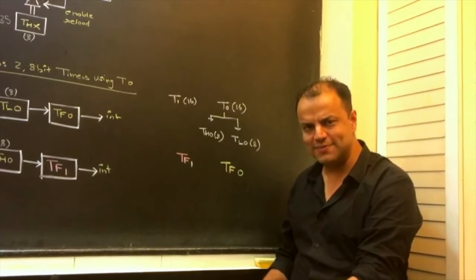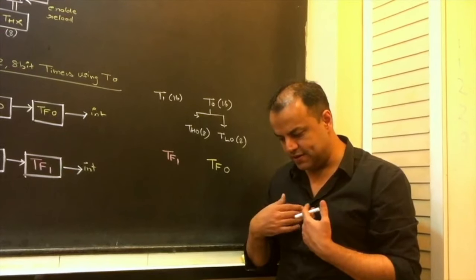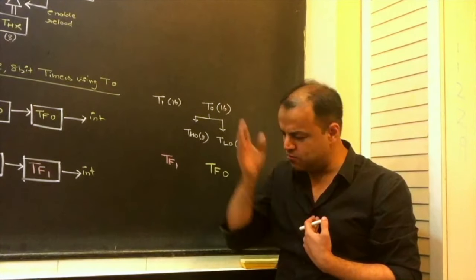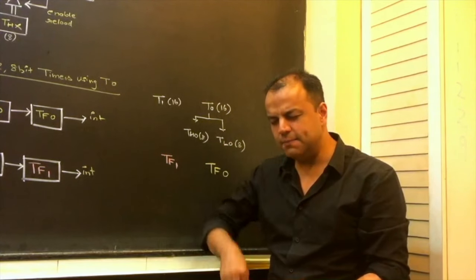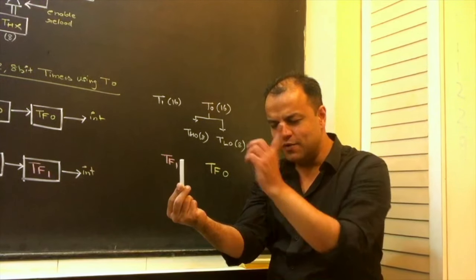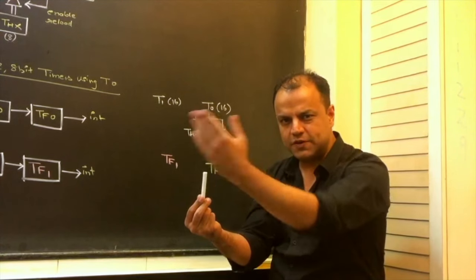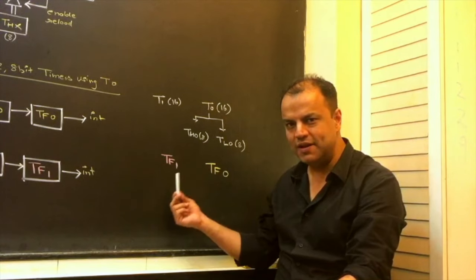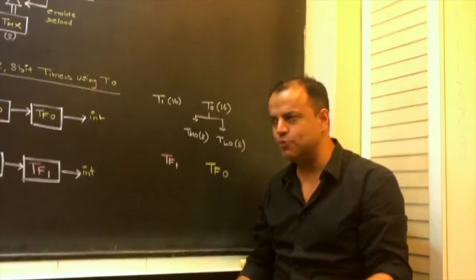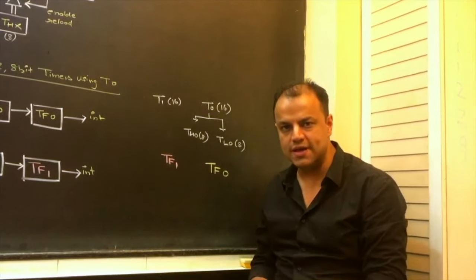Are these overflow flags important? Yes, they are the relation, the connection between the timer and the processor. Timer is counting, processor in its own world. When the timer overflows, it makes the overflow flag 1, which informs the processor that the timer has overflown. So the link between the timer and the processor is the overflow flag. They both don't share one flag. They both have independent flags, which means both can independently overflow. So what you have so far is a beautiful system with two 16-bit timers.